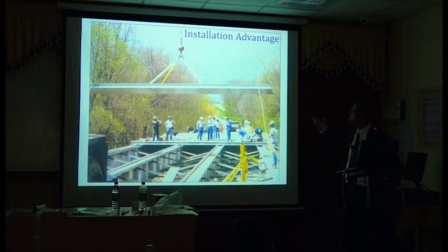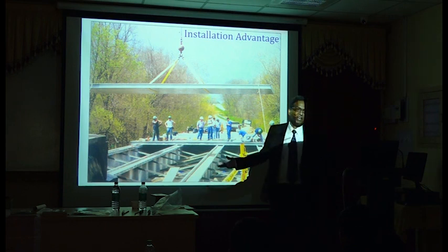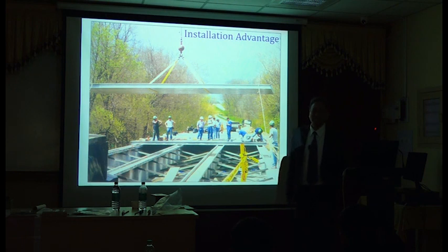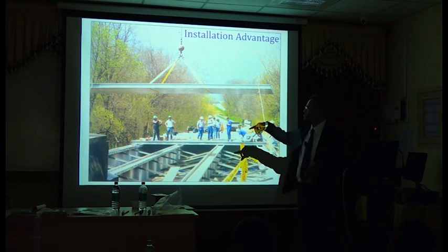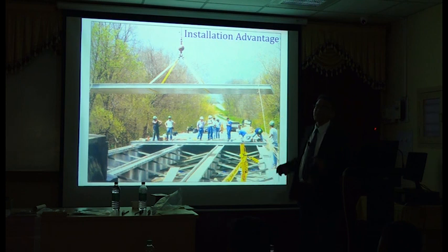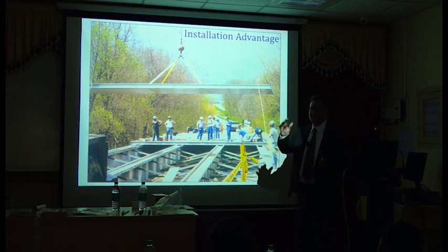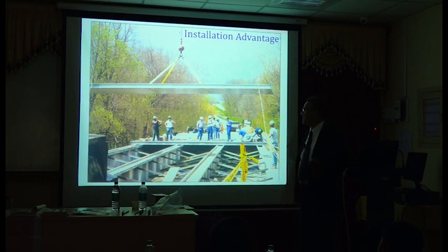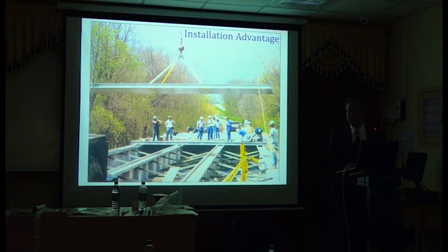Same thing here. In this bridge also, you can see they put together this bridge, maybe 100 feet, about 30 meters or something like that, in less than a day. You can put them all together, everything. So you can start allowing traffic in less than 2 days. That's a very big advantage, because if you are rerouting or closing the road for, let's say, 6 months, that's a big problem. At least it's not acceptable in many of the advanced countries. So if you are able to do everything in 1 week, they are very happy. They are willing to spend more money to reduce the disruption to traffic. So those are some of the situations where you can propose FRP.